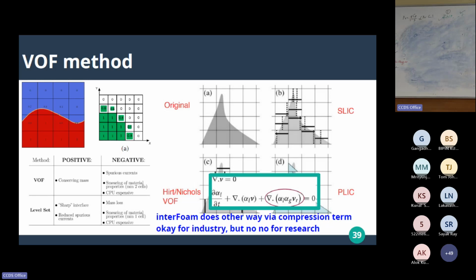By doing that, naturally you smoothen the interfaces and create additional errors, which in VOF techniques people call parasitic currents. It shows additional convective motions around the system. That is the first indication that the solver is behaving very badly. Though you do not have any convective motions around that bubble because there is no evaporation, you still start sensing some kind of evaporation events. It indicates there is some problem with the solver.